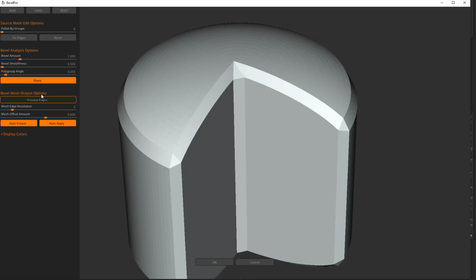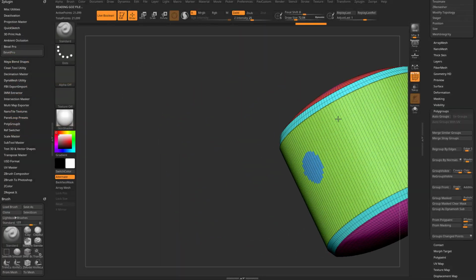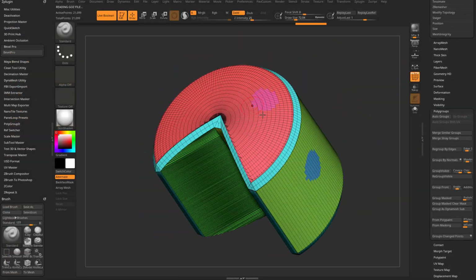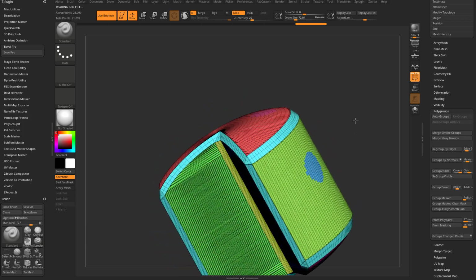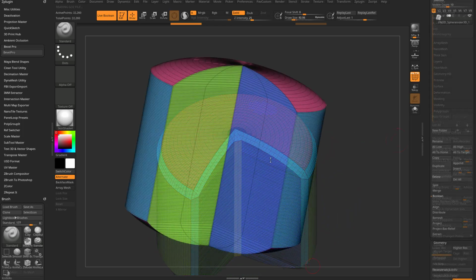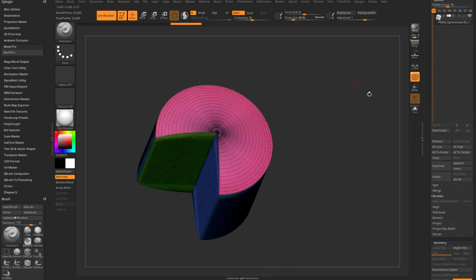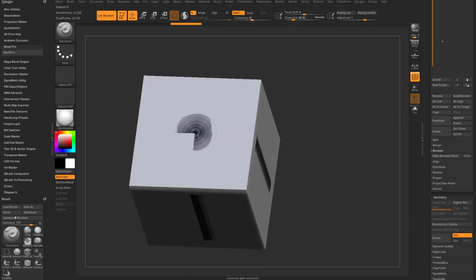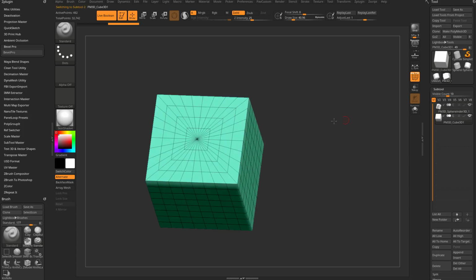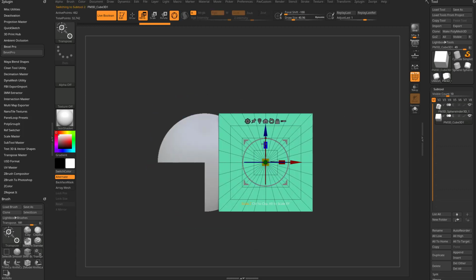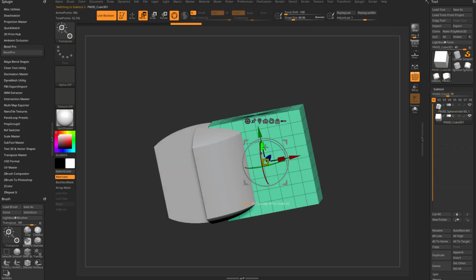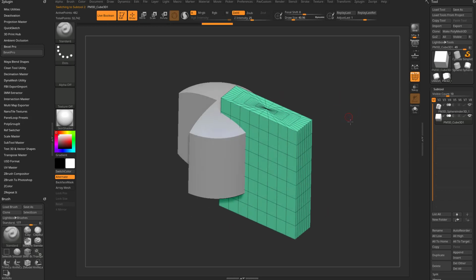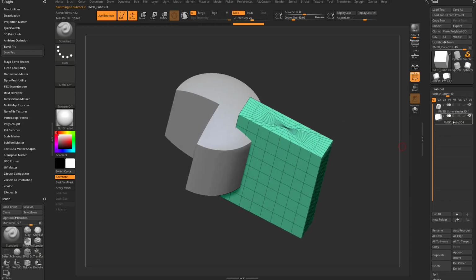And then of course you're ready to go. We can turn on auto apply, everything's looking good, hit OK. And again, Bevel Pro basically ignored these shallow angle areas there. And just back to our original mesh here, we're going to do a really sharp cut. So I'm going to go in here and append a cube 3D, and we're going to take this cube and move it out here. We're going to scale it down this direction, scale it up in this direction so we can get a nice clean slice through here. Turn this into a subtractive mesh with live Boolean turned on.